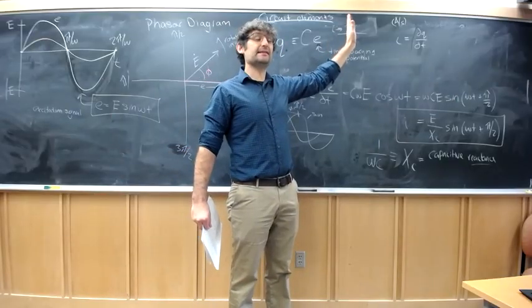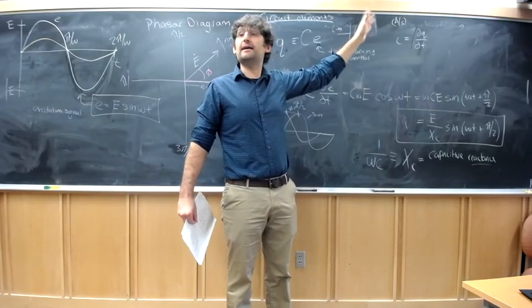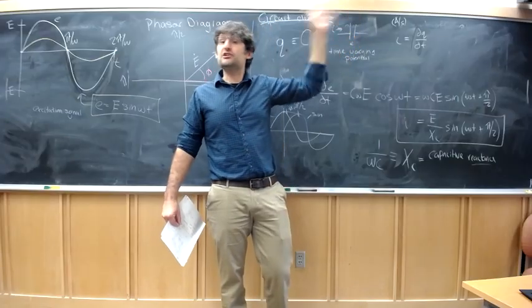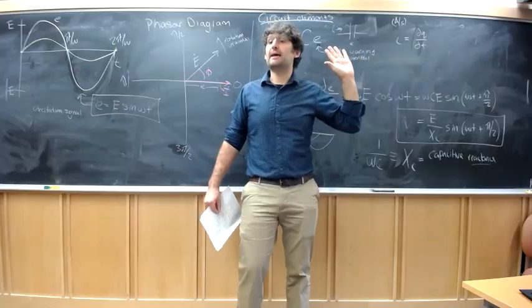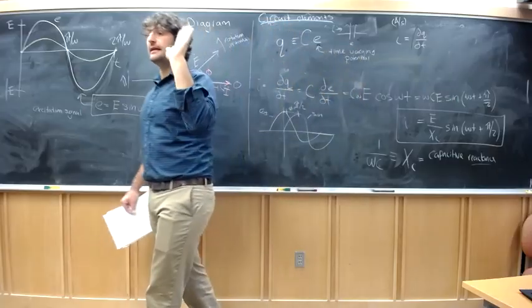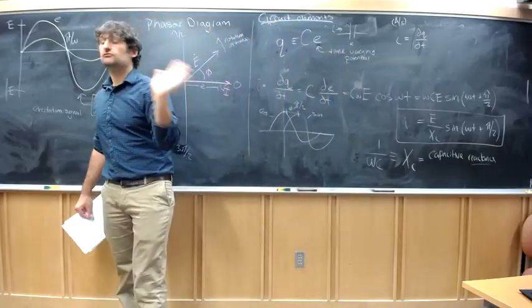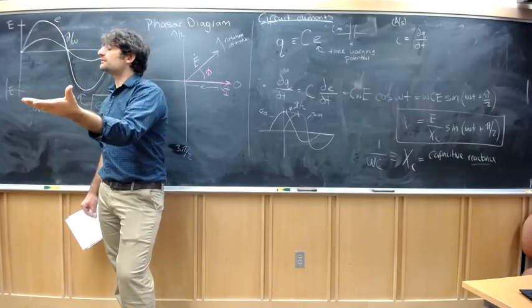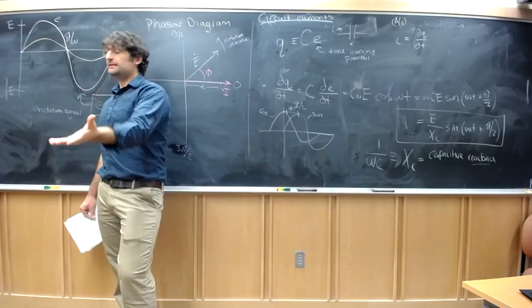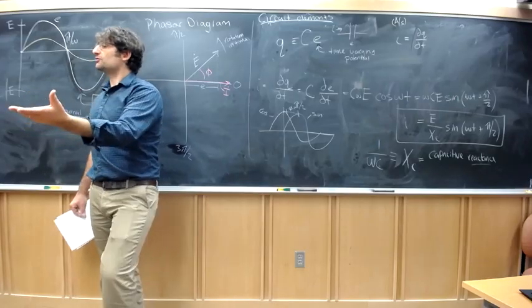And if you do that fast enough, you don't even realize that the plates are there. Because you never put enough charge on to change the potential of the capacitor. You're putting a little bit on, taking it off, a little on, taking it off. You never charge the capacitor, so you don't lose any potential across the capacitor. So it's basically a short circuit as you go to high frequency.